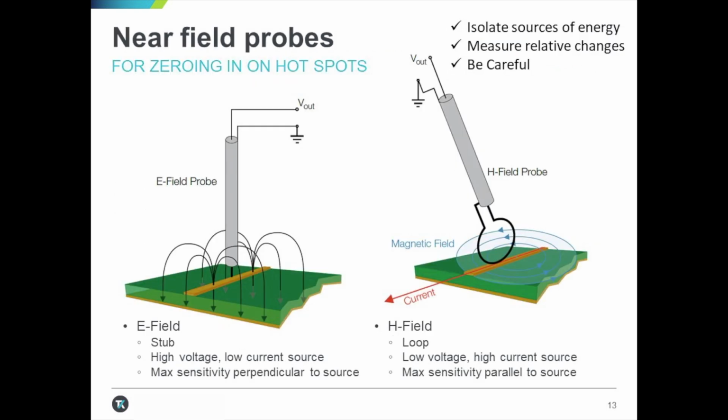While fully certified compliance testing procedures are designed to produce absolute, calibrated measurements, troubleshooting can be performed in large part using relative measurements. Near-field probes are essentially antennas, which are designed to pick up the magnetic field or electric field variations. In general, near-field probes do not come with calibration data, so they are intended to make relative measurements to identify sources of EMI.